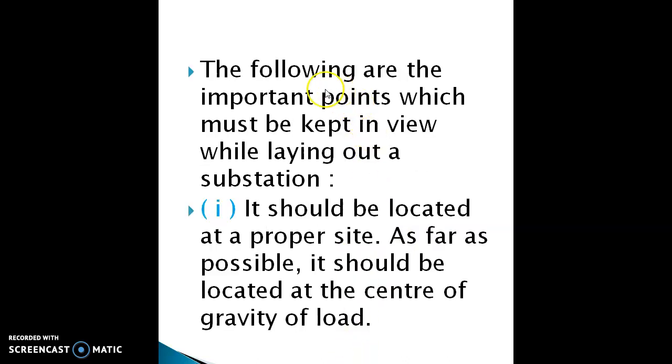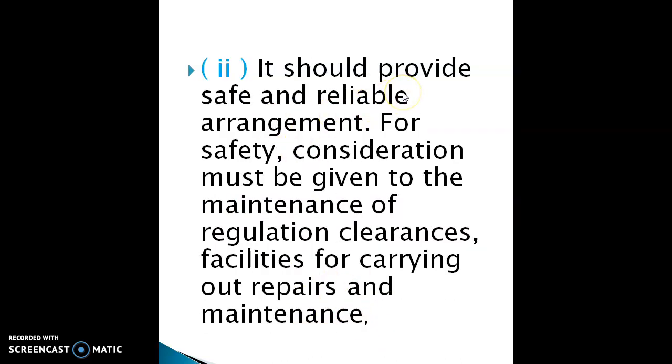The following are the important points which must be kept in view while laying out a substation. It should be located at a proper site. As far as possible, it should be located at the center of gravity of the load. It should provide a safe and reliable arrangement.